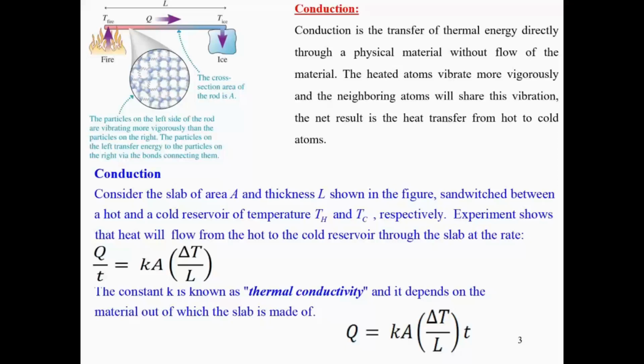So what is conduction? It is the transfer of thermal energy directly through the physical material, without the flow of the actual material. Suppose you heat a rod and the other end is connected to ice. Heat will transfer from high temperature to low temperature, in this direction.